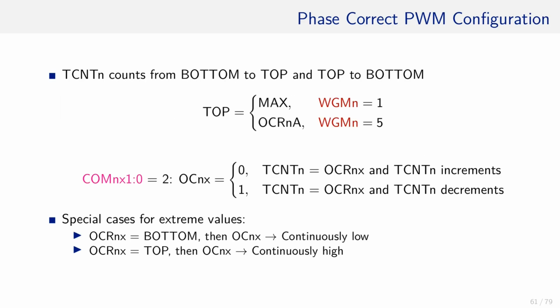Setting the timer in phase correct mode is very similar to earlier configurations using the WGM bits in the timer configuration registers. They need to be either 1 or 5. COMnX chooses between a normal or inverted waveform like before. Do not forget to configure the pin to be an output port, otherwise no signal is emitted. Like in the fast PWM mode, the top can be set manually using the OCR. In that case, there will be no PWM available on the OCRnA pin.